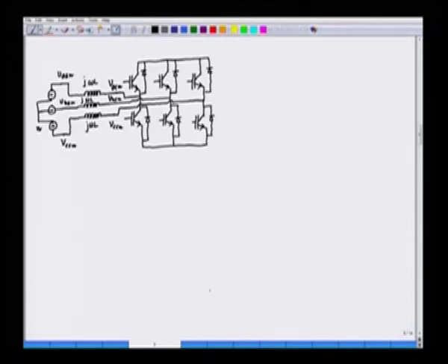And this is connected to the DC link. The DC link comes in between. So, we have the DC link here which is having a capacitor and then we have the load end converter, and that is similar to the IGBT front end converter. We have a similar structure in the load end. So, we have the same structure here.